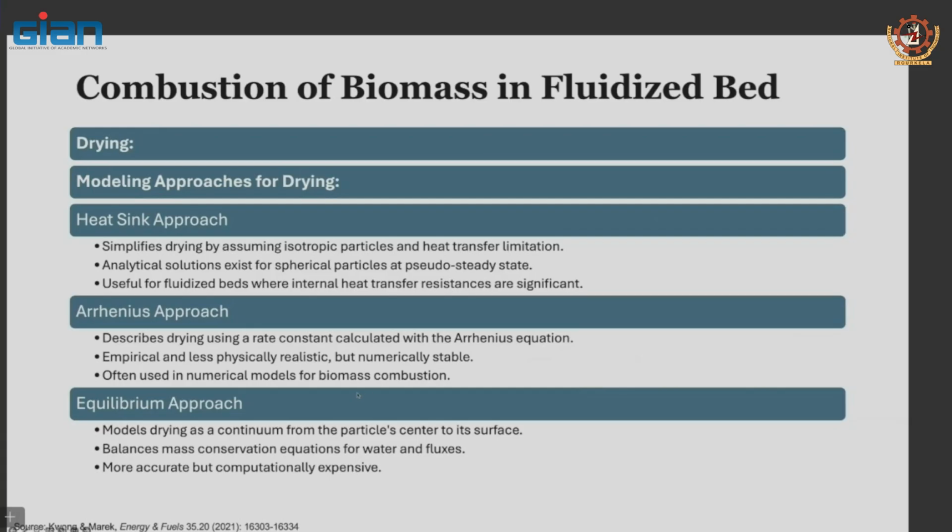Heat sink approach, useful for fluidized beds where internal heat transfer resistances are significant. Nevertheless, for numerical modeling, as I said, this gives us a linear approach, which I prefer because it reduces computational time and calculations are more straightforward.